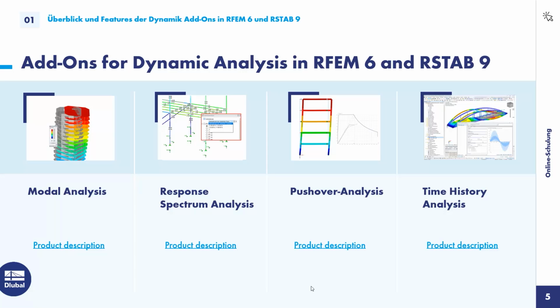And with that, the rest should be automatic. That means you get an envelope of results for the modal combination and the directional combination. And the final result is already automatically inserted in the seismic design situation. That means it's just considered in the design.